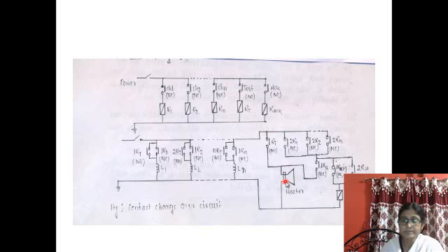In order to resist that, there is another contact of RH, that is NO type contact. Whenever this is de-energized, even after releasing this acknowledgement switch, this contact will make the path. Through this path, the RH will remain in energized state until it is forced to go to de-energized state.